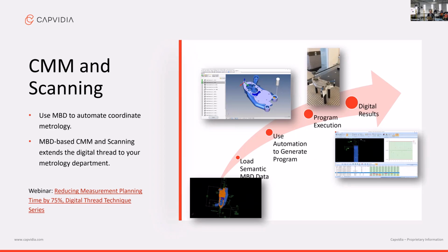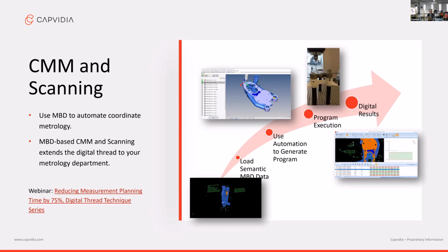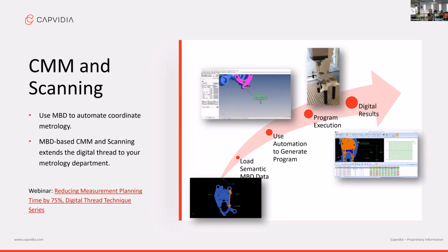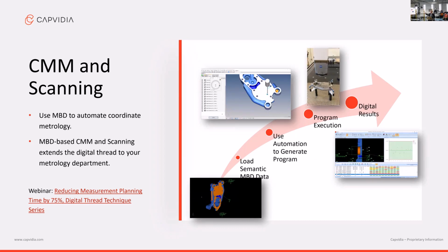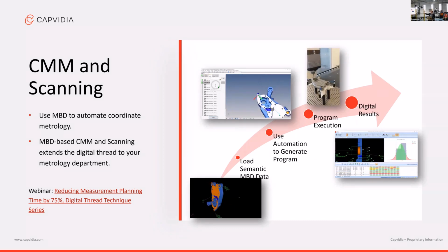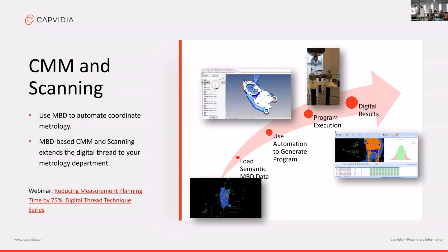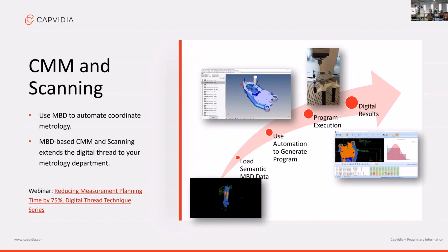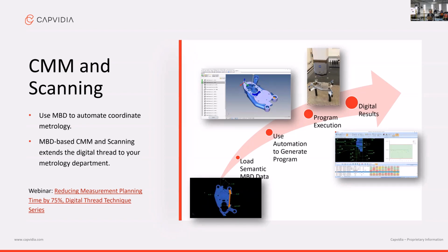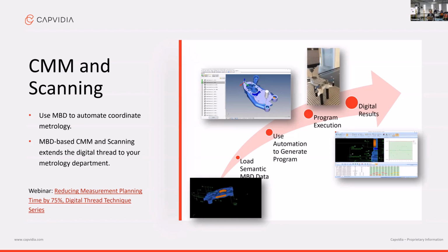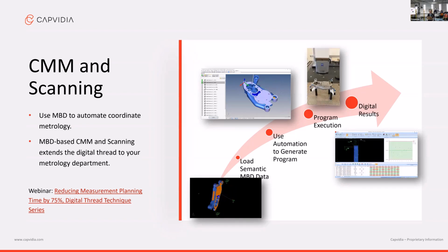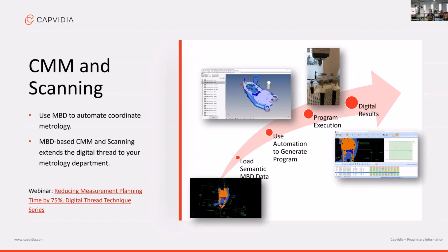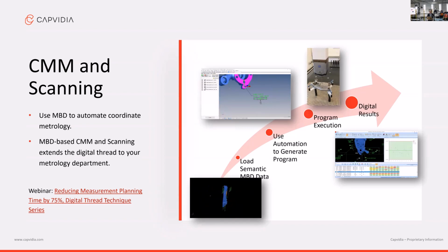The obvious one is coordinate metrology of all types, CMM, or maybe scanning. There are a lot of really cool devices around here. We have a CMM, obviously, an X-ray CT, an arm scanner, a blue light scanner. All of these things at the end of the day are point collectors. And you collect your points, you analyze them against the GD&T that's on the model. This is driven by the MBD, by the 3D annotations or the annotations that are placed on the drawing. So they're an essential part of driving a CMM type of workflow. So this is a big application area for model-based definition.